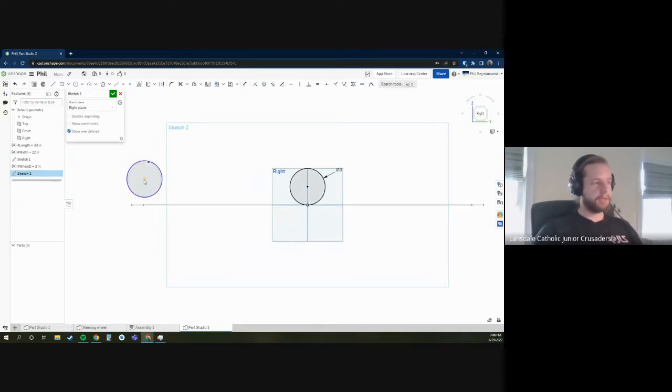Normally you'd think, oh, you want to put this wheel directly on the flat surface. Well, when you're dealing with a skid steer or tank drive robot, if you have all 6 traction wheels on the floor at one time, and you have a thinner robot rather than a wider robot, the front and back wheels will actually work against your rotation.